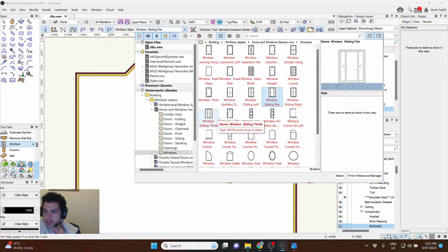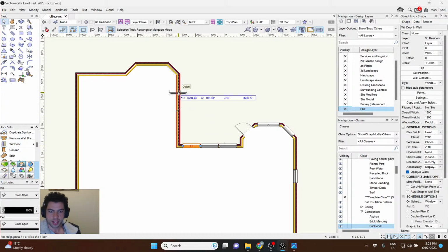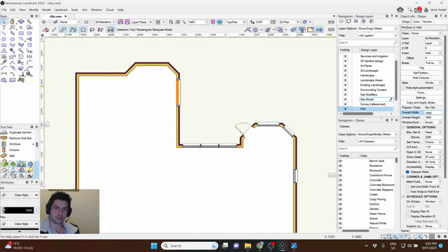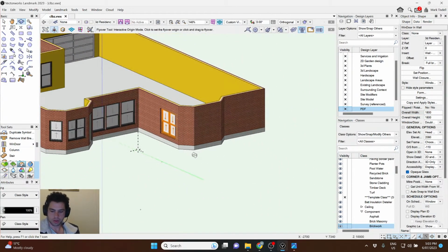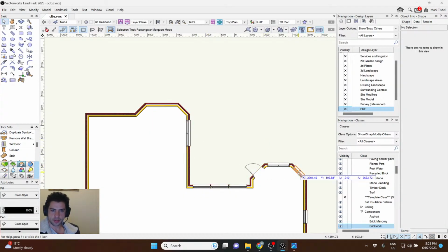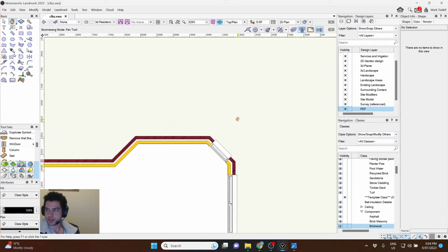What are we going to go with here? I think these are very interesting windows. I think I'm just going to go with these. Actually, I could probably just copy these bad boys out. Boom. Right there. Width, we'll go 1500. Oh, this one might be like 1800. And I'm just going to check it's inserted correctly. Yeah. Cool. Now we've got a real skinny guy over here. And I'd say he's even narrower than that. Let's go 700 mil. Should do.